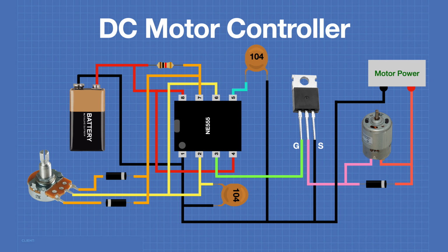Now here's how we'll hook up our circuit. We're using the 555 timer in an astable mode. The frequency of the output is determined by the 0.1 microfarad capacitor tied between pin 2 and ground, and the resistor tied between pin 7 and the VCC. The pulse width is dependent upon the position of the potentiometer, with the 2 diodes modifying the pulse.